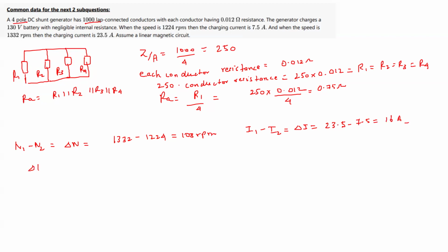So what is the change in the EMF? Change in EMF is delta I into RA, which is 16 into 0.75, which is 12 volt.